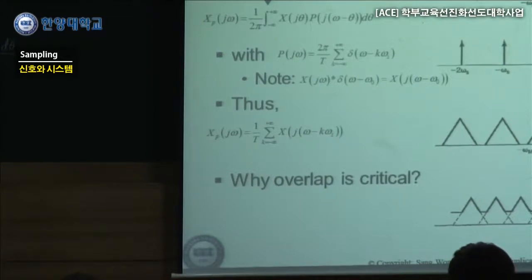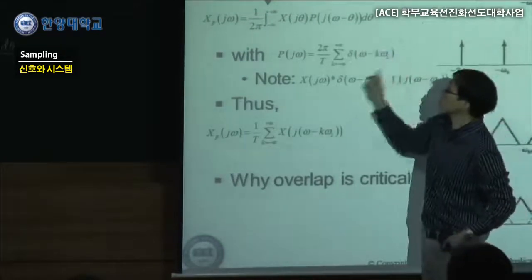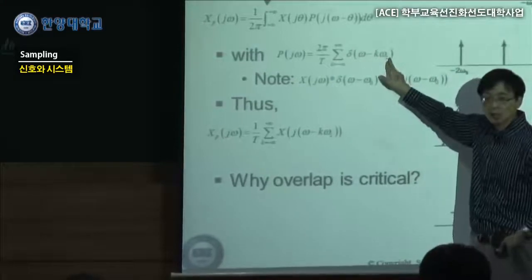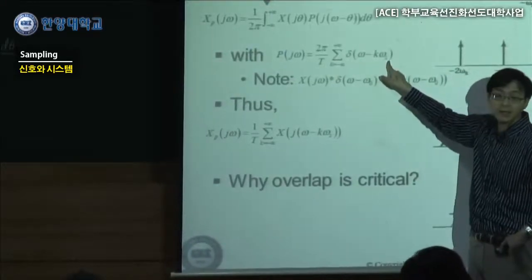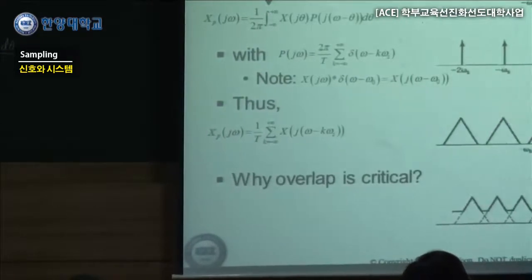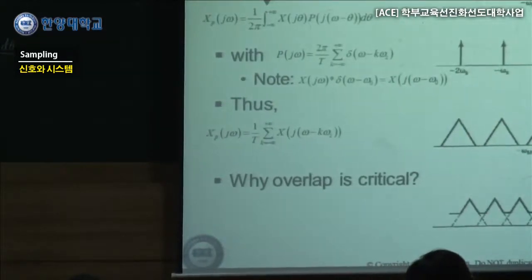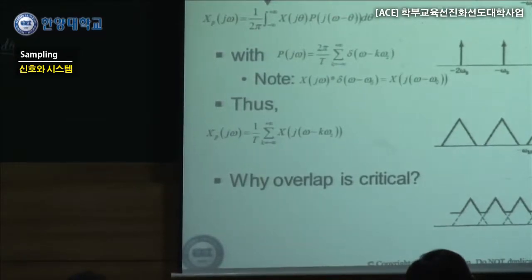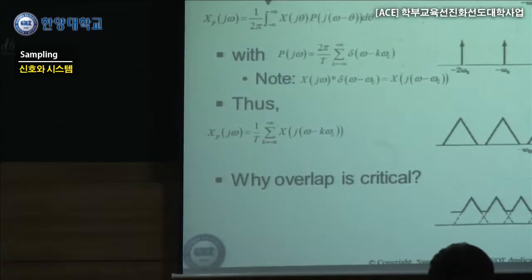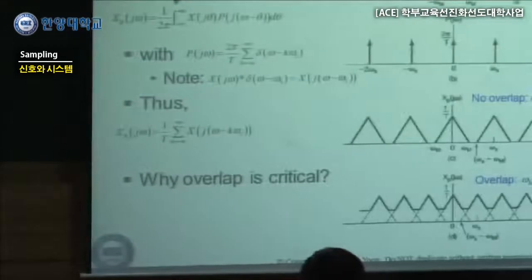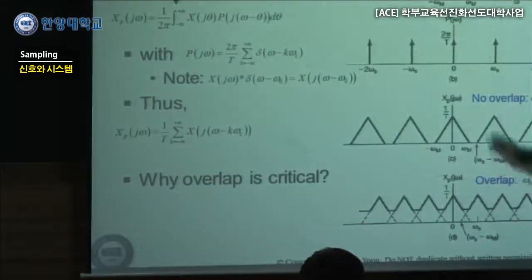And we can also think that this one is actually the same as the impulse train in frequency, equally spaced by ω_s, like this, spaced by ω_s, having some scale factor over here. And then if you multiply and do the integration, if you do the convolution between them, how do you feel?